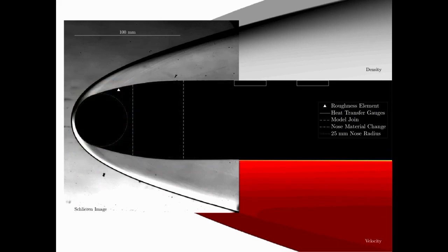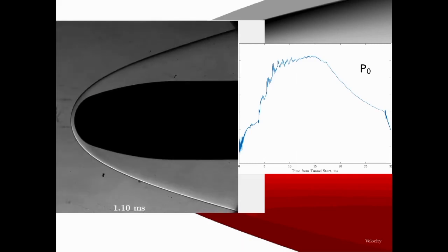So that's what I've just said. If we just have a video, it's an actual experiment. What we're looking at is tunnel runtime. Pressure ramps up at the start. You get a bit of steady runtime about now. It lasts for about 6 milliseconds. Doesn't seem much, but it's plenty. And then you get the slow ramp down. I don't think you can quite see it.